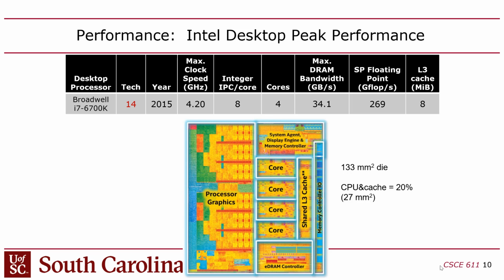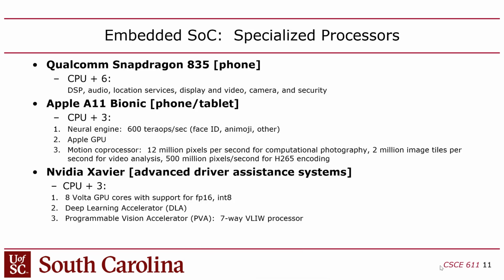Yes? I believe there should be some input-output, like memory controlling or some kind of outside output. And when you have those transistors, they have aluminum wiring from that transistor, and then they can spread them to one side or spread them on the whole square side and then solder the pins. Yeah, that's basically what I'm saying. And you have to wire up the pad frame. If you want to get access to the cores, you do not necessarily have to break the package. They test their chips by sending special signals to the pins and reading the response. Yeah, I used to do that too. I used to have little micro positioners, and we'd actually put a little probe down directly on a pad to test chips. Okay, and here's one more example, or actually two more examples.